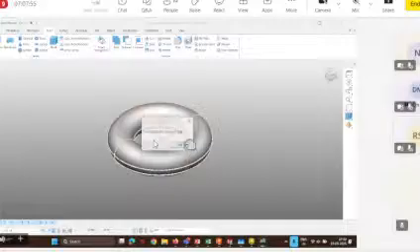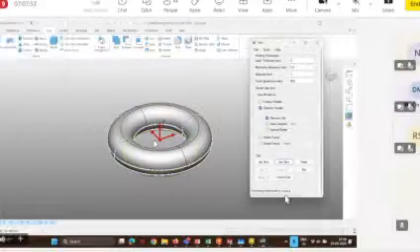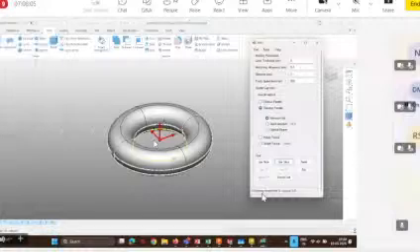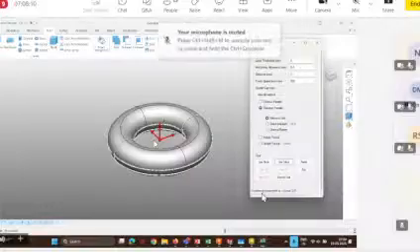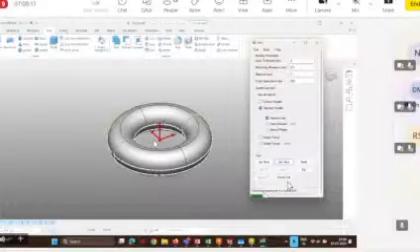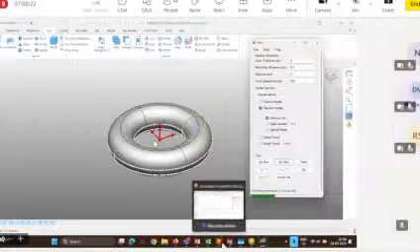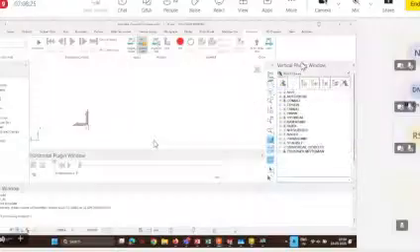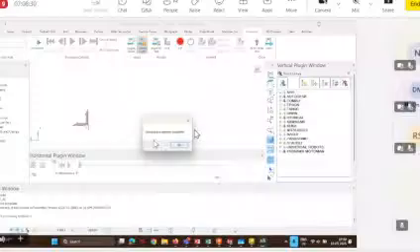So it's hit. Now if I go back, it's doing this overhang treatment, just checking wherever it's required, and only there it's generating this tilt angle. Once it is done, we can directly go back to PowerMill to generate the toolpaths. In PowerMill, there's an option called the robot plugin, where you can select different robots, even the standards like ABB, KUKA, Fanuc.